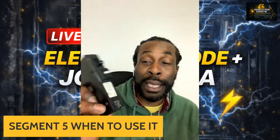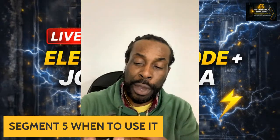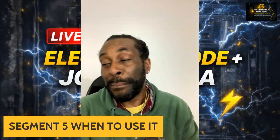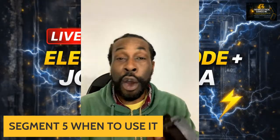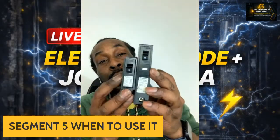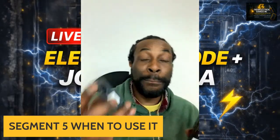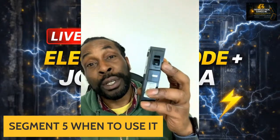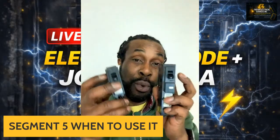Once connected properly, as you can see, you have the white that goes on here, and you have the hot that goes here. This is an arc fault type breaker, and this can only be used in a Schneider panel. These are the same family. The only difference is this is an arc fault and this is a regular breaker. This protects your wires, and they both will protect your wires.